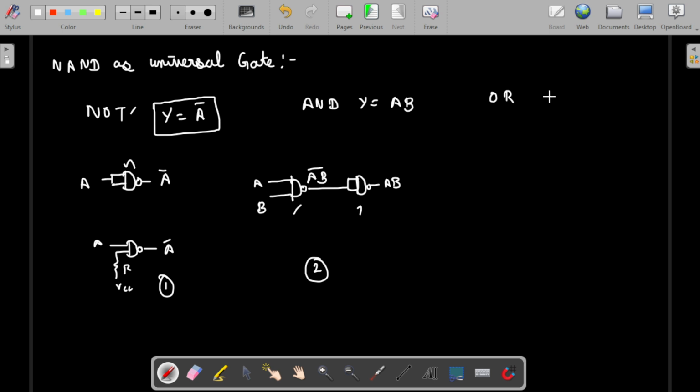So here the OR. So OR is A plus B, right? So how we can get A plus B is that, using De Morgan's principle, let's take a double bar. If we take a double bar, it will be cancelled, then no issues. So if we apply De Morgan's law to the inner bar, then we will get A bar plus B bar, B whole bar. If we again take the bar, that will be A plus B. So okay, this is the quiet thing that we will be getting here. So if we take that bar twice, then the output will be similar to this one.